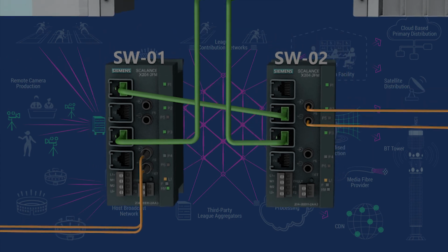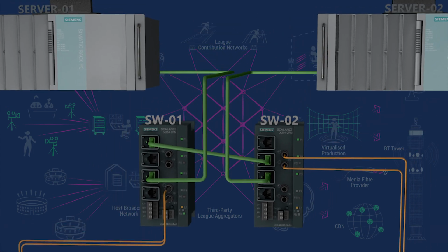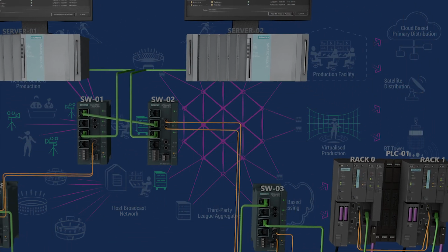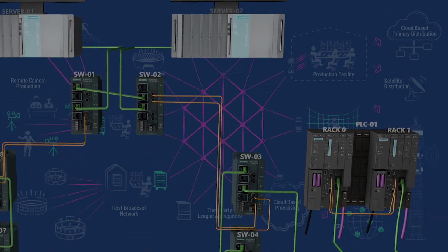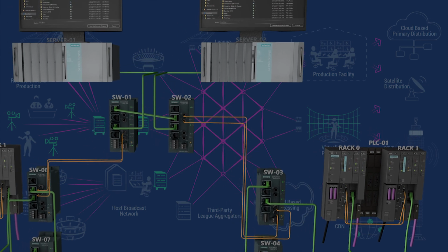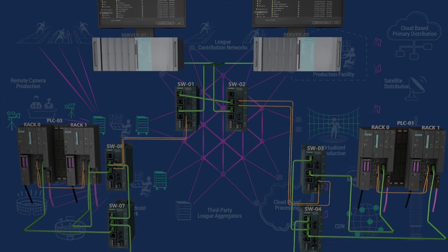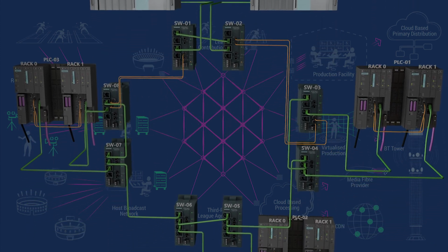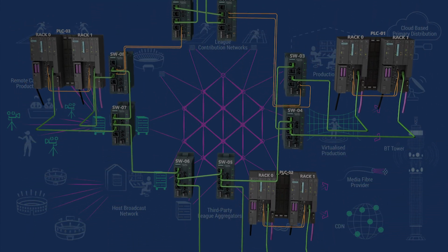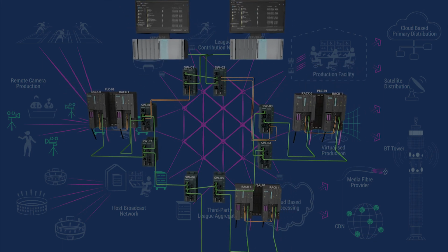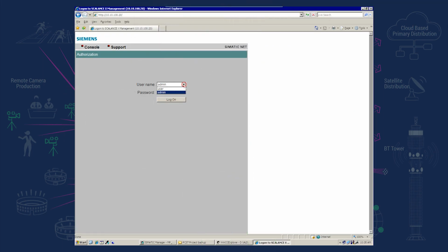Selection of ring ports depends upon the distance of network switches and speed requirement. If the distance between PLCs and server is long, then it is better to use fiber optic. If the distance is short, then usually an RJ45 cable is used. But if in a short distance there is a requirement of high speed communication, then it is preferred to use fiber optic in place of RJ45.